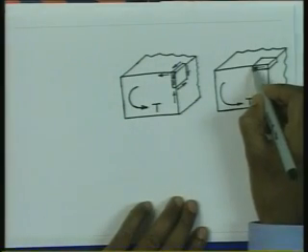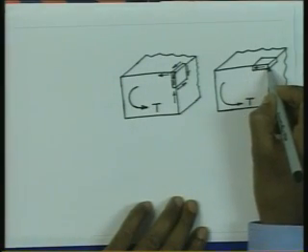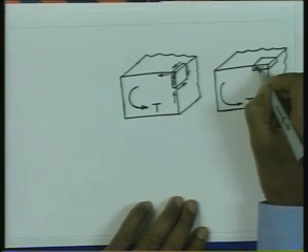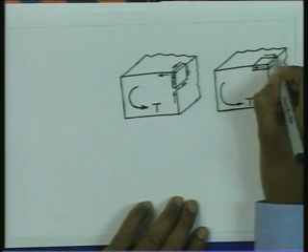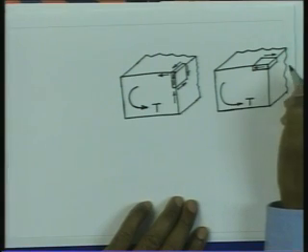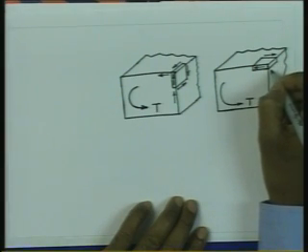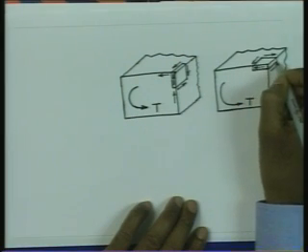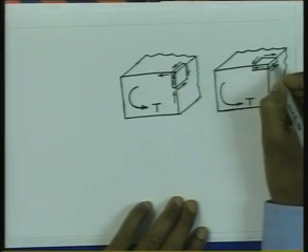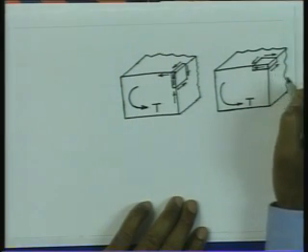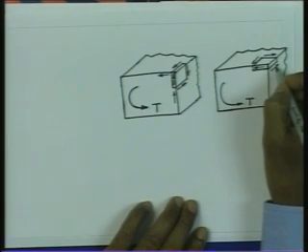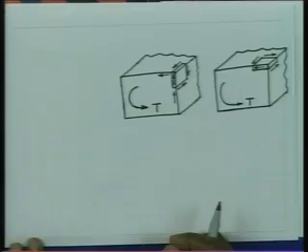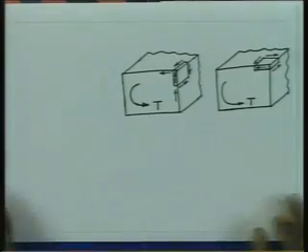By a similar type of argument, if non-zero stress is going to act at this point in this direction, then on the opposite face we will have stress acting like that, and the complementary shear stresses are going to act like this on this outer face. Since this outer face is again free of any external loading, this stress is 0, therefore this is 0, so also this and this is 0. So, therefore, we will find that the stresses are going to be 0.